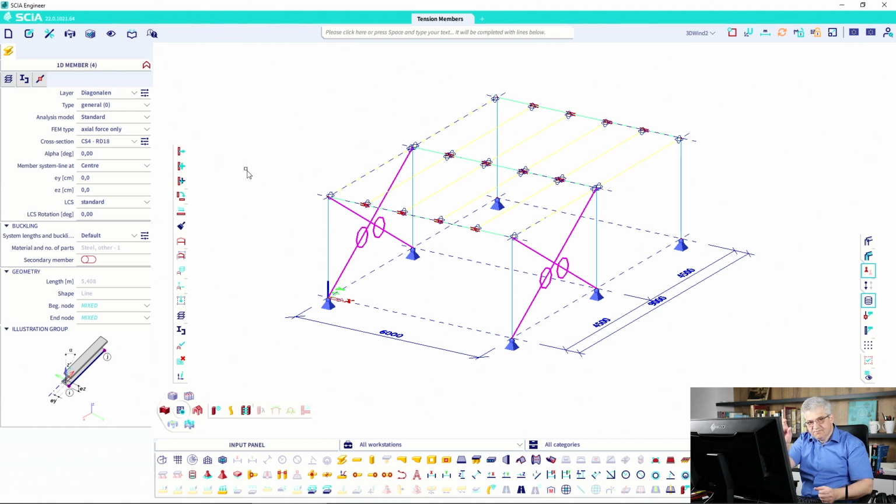And if we would split these members to, for example, 5 or 10 finite elements without the bending stiffness, they would collapse also for small pressure force. So that means they have only one finite element. This is an advantage, for example, for the stability analysis, because they don't get local buckling shapes.